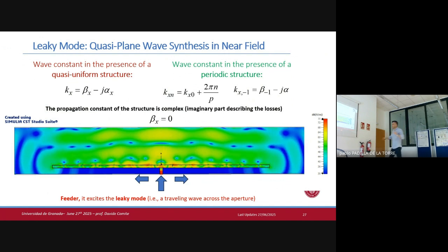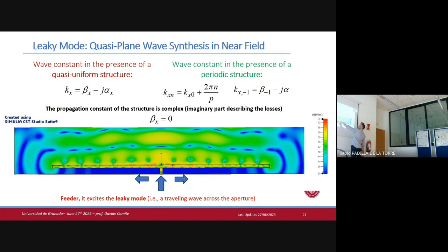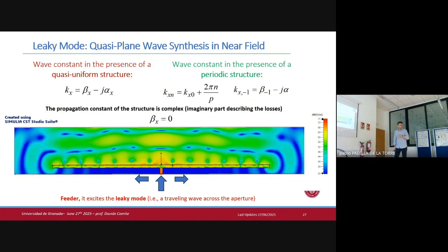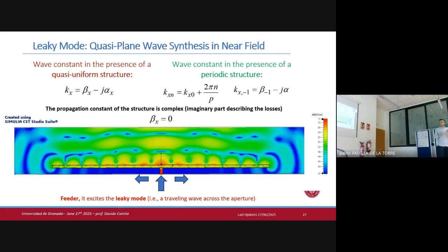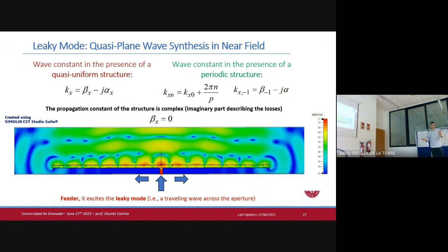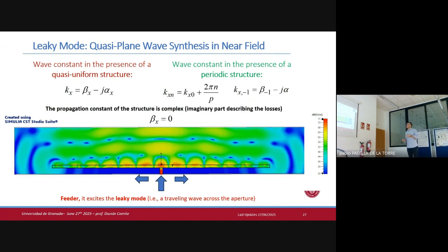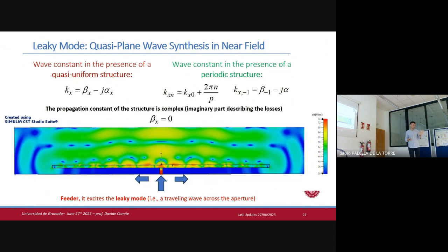But since there is a leaky mode, look at this. Look at the amplitude here. It's modulated, because there is an exponential decay. Okay? So even though I have an antenna that is planar with a well-integrated source, I can use SIW, as you well know, I can use different approaches. I am getting the farthest possible illumination with respect to the uniform one.